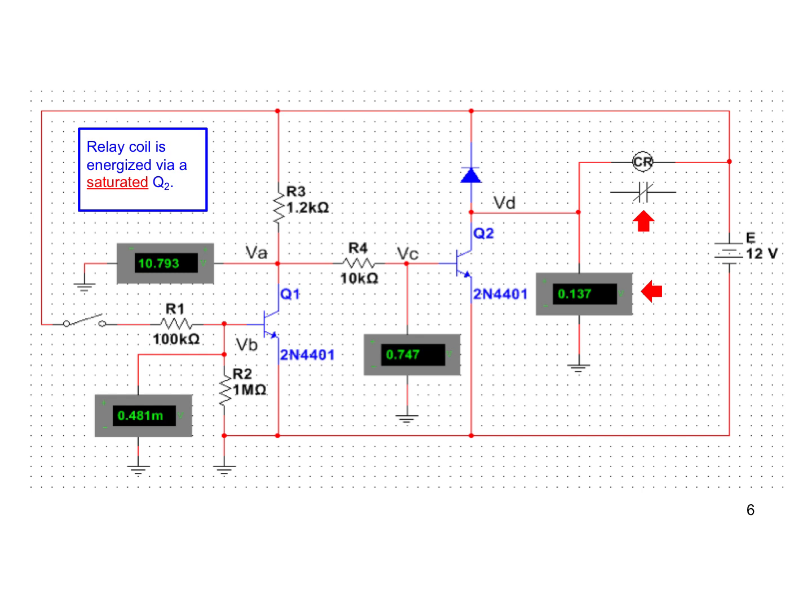Okay, so anyway, this is just a little different picture. I showed some typical meter readings. You can see here with this open, the base voltage here, VB, is essentially floating. So this is less than half a volt, so that's essentially zero. Okay, and our current path is down like this. We know that the base to emitter junction is working, okay, because that's totally normal.